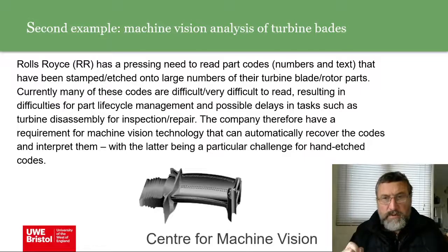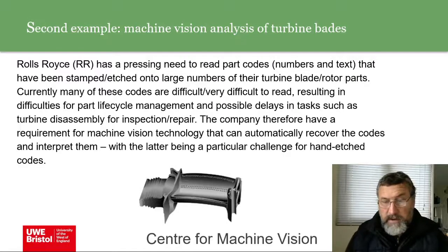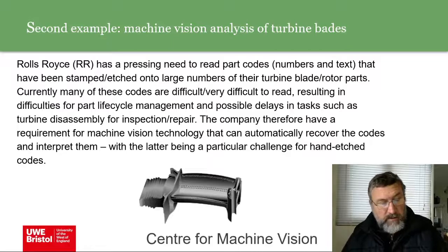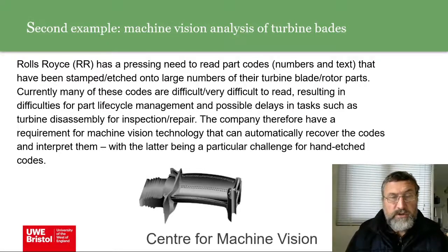So we can use some of our three-dimensional high-resolution techniques to recover that. Even if there's marking or pigment, or debris, a certain amount of coloration on a part, we can still see the 3D marking because we can remove, with our techniques, the 2D pigment from the 3D shape or texture.